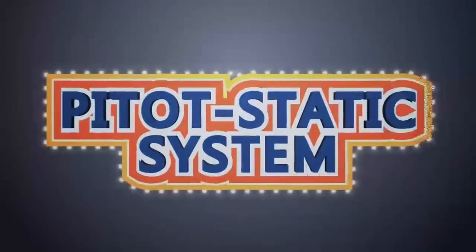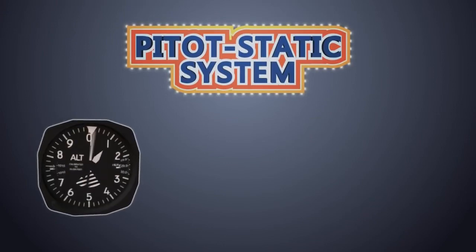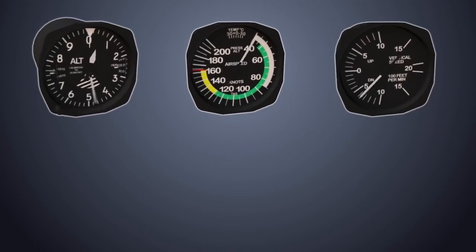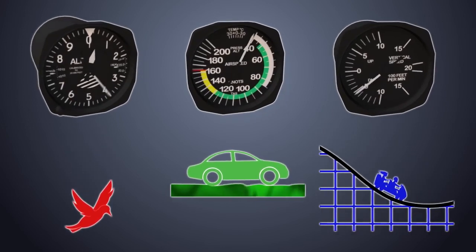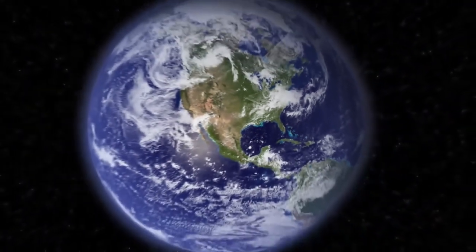The pitot-static system. The pitot-static system is connected to the airplane's altimeter, airspeed indicator, and the vertical speed indicator. These instruments tell the pilot how high they are, how fast they are going, and how fast they climb or descend. These are determined by measuring the pressure of the atmosphere.